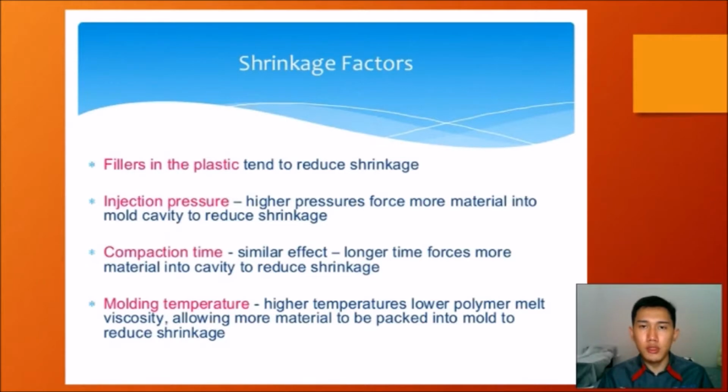And lastly, molding temperature. The higher the temperature, the lower the polymer melt viscosity, allowing more material to be packed into the mold to reduce shrinkage.